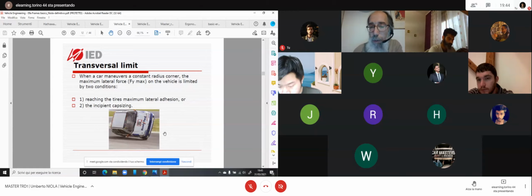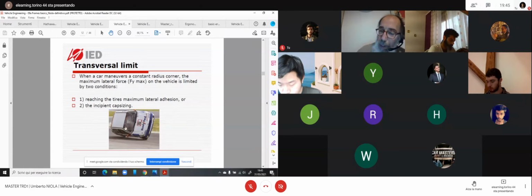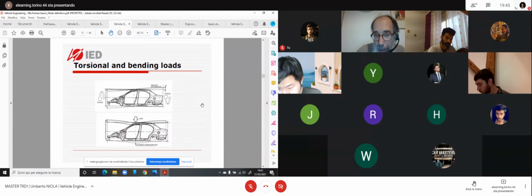For the standard and also including some exceptional solicitation for bump or other things, a good starting point is always to consider 3 times the real weight of the car to calculate the effort and stiffness of the mounting points, suspension element, and other things like this. Okay, this is for basic information. So if you start with 3 times the weight of the car as the force stressing the elements of the car, this is a good starting point. Okay.